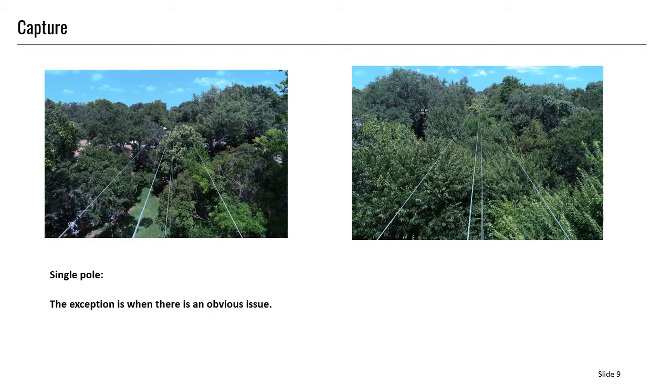Single pole distribution inspection capture is relatively straightforward and allows the operator to move from one pole to another very quickly. Without a beyond visual line of sight waiver, it is still the easiest method. You fly one direction and then you turn and fly the other. Since each photo captures the lat long in the photo's metadata tag, its relative position stays with the photo.